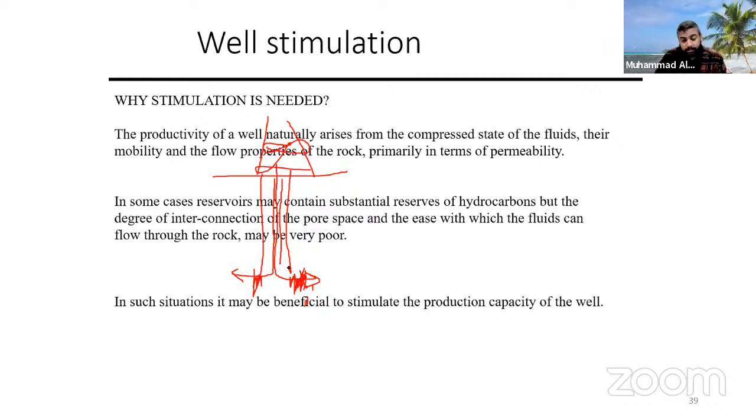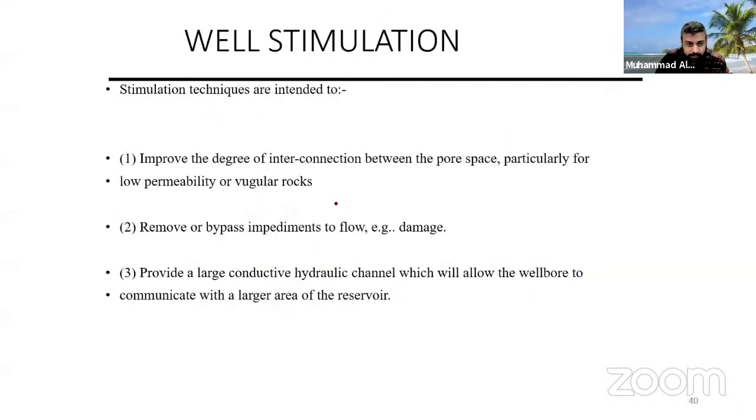So we artificially stimulate. We do the fracturing, like smashing a window and cracking it, making holes out of it. We send a hydraulic fluid down, which fracks this area to create artificial permeability. This is one of the jobs of the production engineer: the hydraulic fracking or acidizing job in order to do the well stimulation.